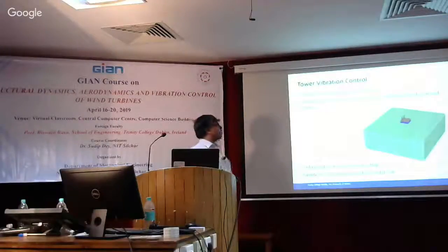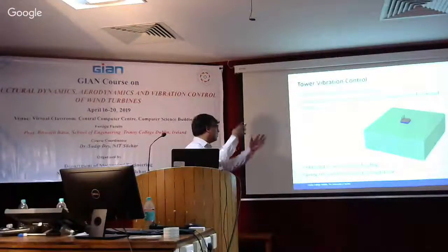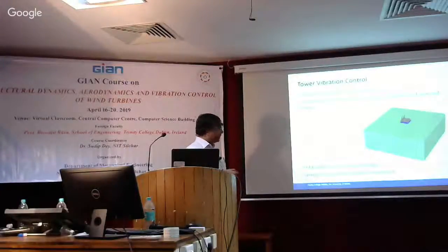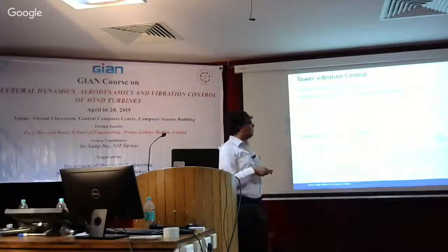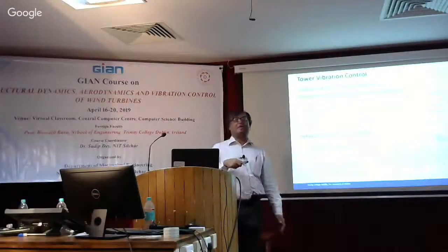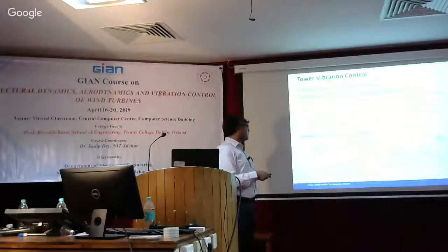We also looked at some soil structure interaction. If there are people from civil engineering here, we're interested to see how the foundation gets affected by the dynamics and how you can do the integrated system. And obviously the influence on the structural response, including soil structure interaction, is significant. You can see here, SSI and OSSI. Particularly if you design the controller without the soil structure interaction, it may become ineffective when the soil interaction happens. So you can see that this is uncontrolled and passive in OSSI, or soil structure interaction. Now we have an uncontrolled system. We have a passive TMD here with soil structure interaction.